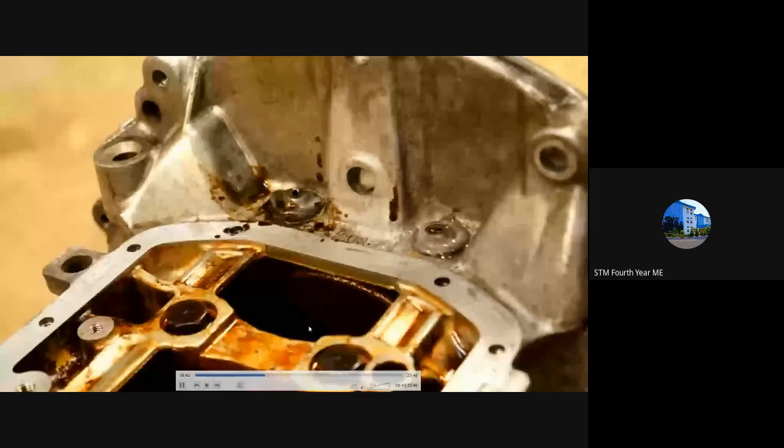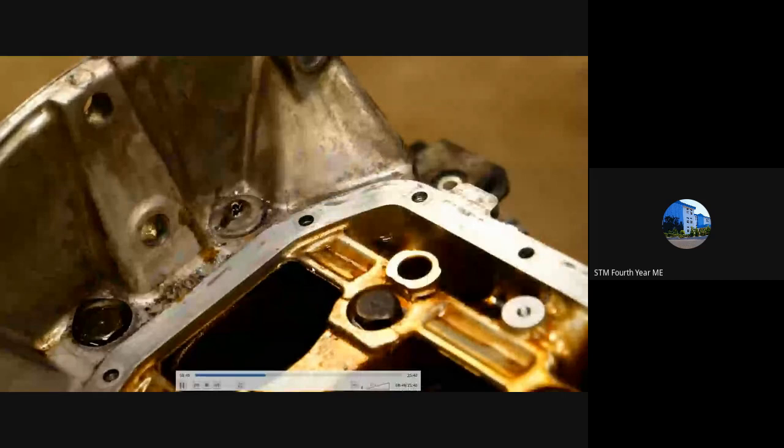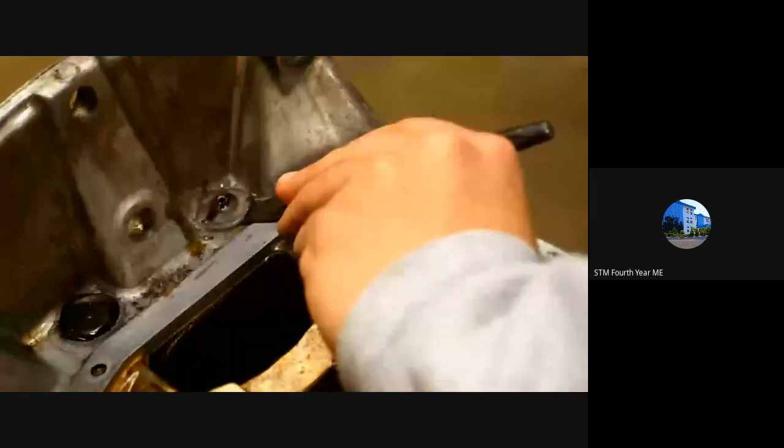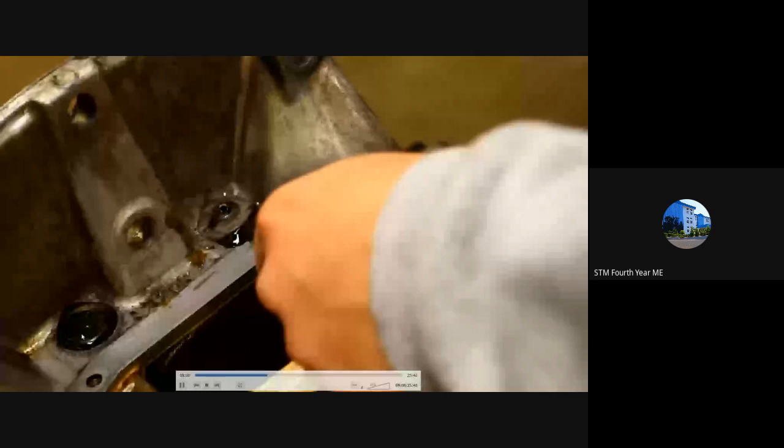Okay, so we had to remove. For removing the crankshaft, we had to remove the bolts, and this is a flywheel case that is inside, and this is a cover that is on here. It's a cover here, and we are removing the cover for exposing the bolt inside. So you can see the oil that is present earlier is present inside the cap itself. So this is how the oil lubricates inside. So oil must be present in all these parts for sufficient movement of the mechanical parts. The oil is wedged in between the caps also. So you can see once the cap is removed, there will be a bolt here. See, there is a bolt head here. In the same way, there will be a bolt head there.